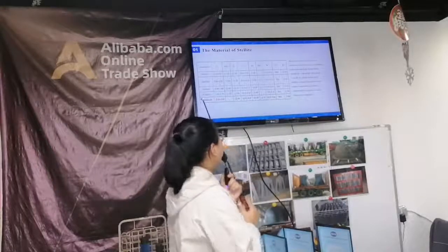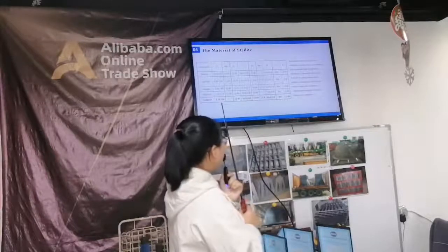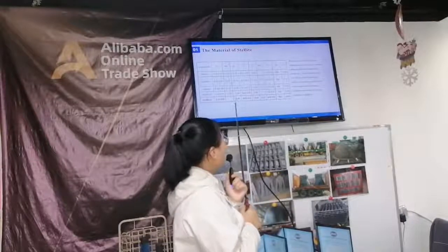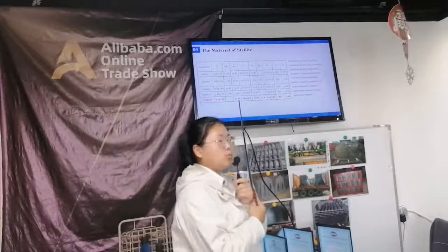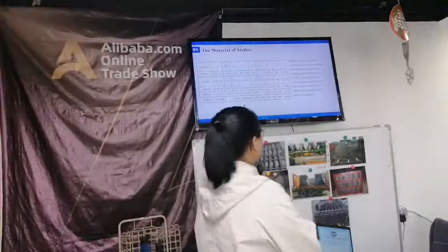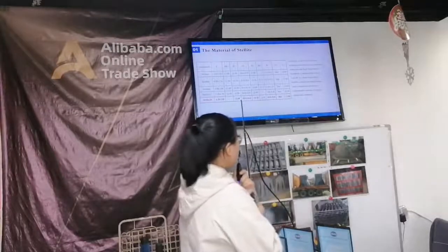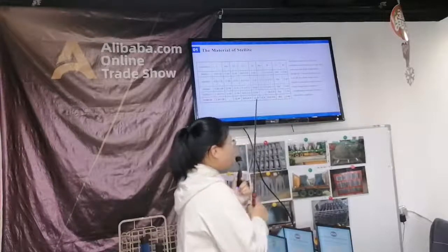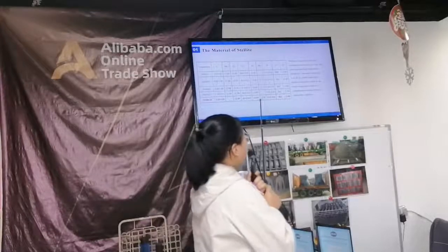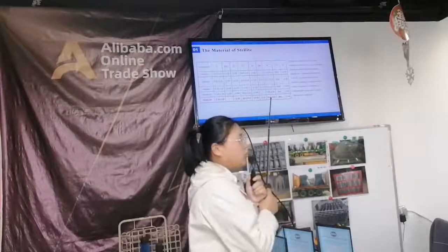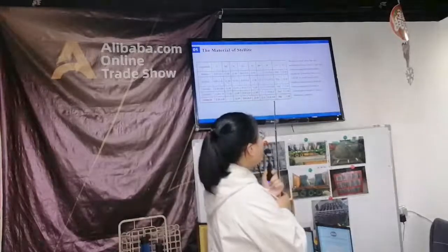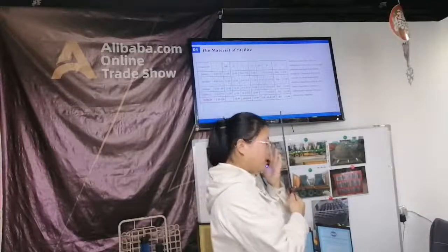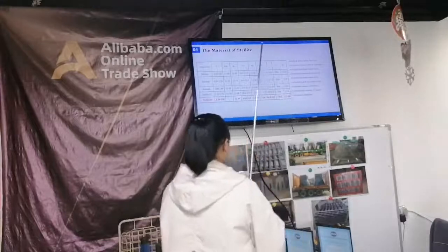Stellite 20: carbon is 2.2 to 3.0%. Silicon is less than 2.0%. Chromium is 30 to 34%. Nickel is less than 3.0%. Tungsten is 14 to 18%. Iron is less than 3.0%, and the cobalt is balanced.